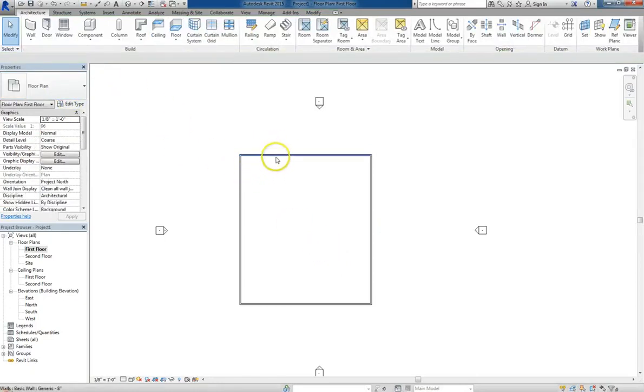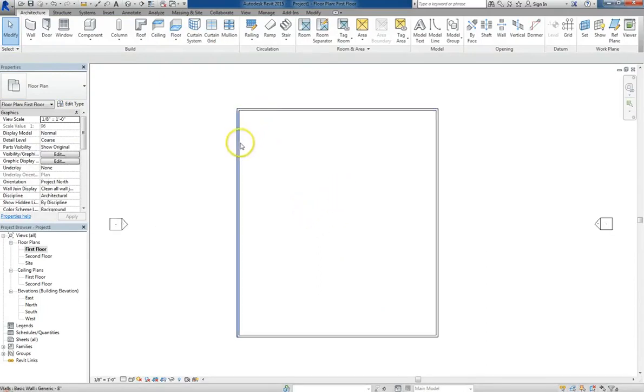Now, when we go to add in the floor plate, one of the things that people always ask me is, does the floor go to the outside wall or the inside wall? And really that's going to depend on what type of construction you're doing. If it's going to be on a platform, if it's residential, some floors might extend all the way out and have the walls sort of resting on top. Others might be like skyscrapers, where the floors extend out to the wall, but the wall itself is outside the floor. So ultimately, the answer is going to depend on your project and what your needs are at the moment.